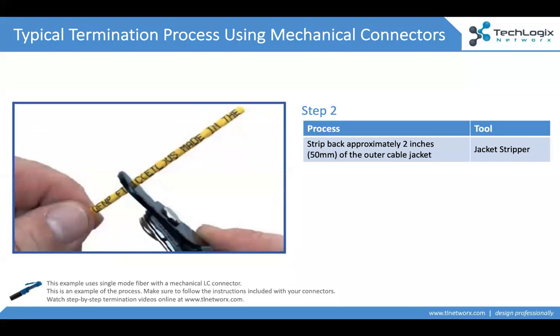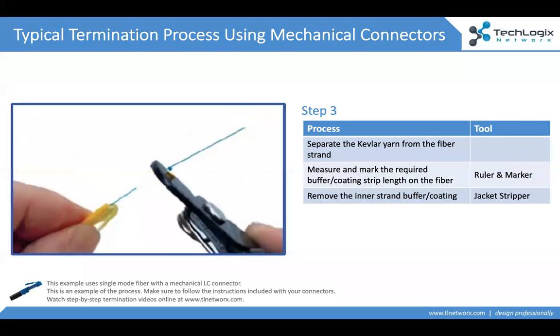So first thing we do is we cut the fiber, put the end of the connector onto that cable. Now we got to start prepping the cable for termination. This is where our 3-hole stripper comes into play. We're going to cut that outer jacket off. And usually you want to take 2 to 3 inches of that outer jacket off. It exposes the internal strand, okay?